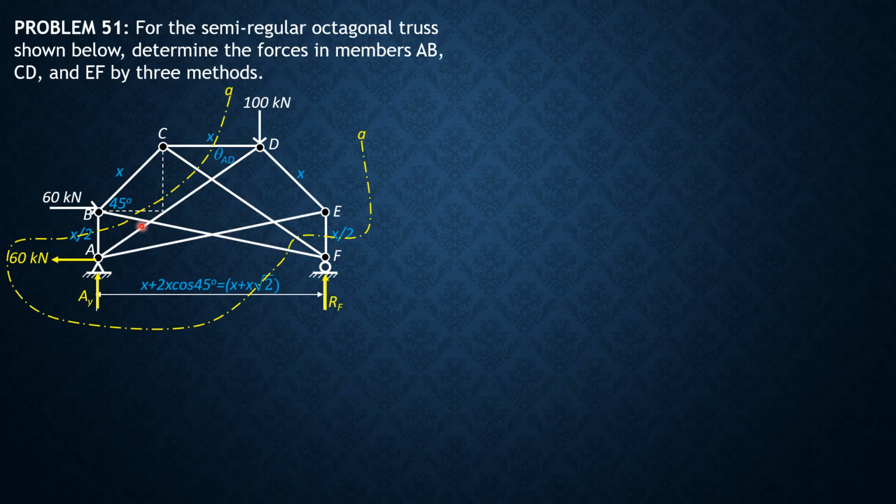We put two force bodies, so they are in equilibrium by themselves. So we put arrows that are equal and oppositely directed. Don't mind the members that are cut twice. So these are the forces inside the cutting section. Then let's extend the lines of action of AB and CD. Call the point of intersection between CD and AB as L, and between CD and EF as R.